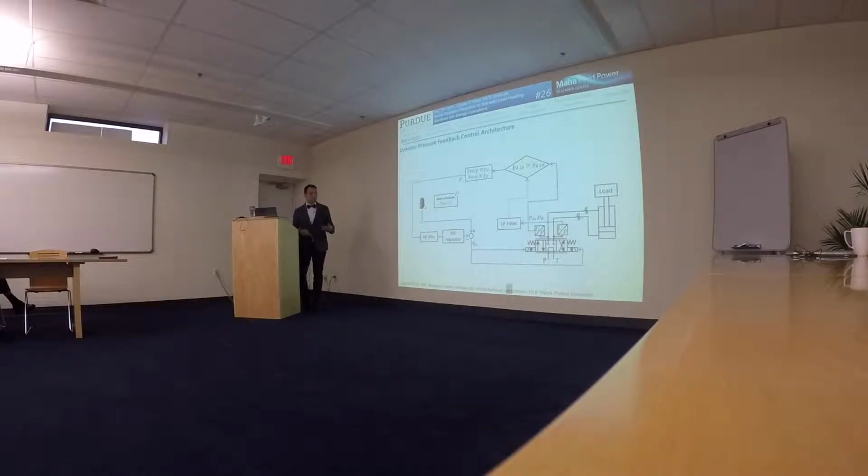And this methodology is implemented by using a gain scheduler. And the gain scheduler is indexed by the low pass filter pressure, which gives an indication on the load conditions of the machine, and by the operator command, which indexes the operation of the machine. And once the operating condition is identified, this helps the PID to select the proper parameters for that particular operating condition. So before going